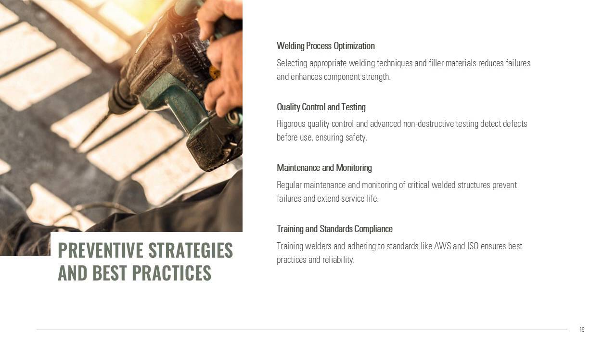Implementing rigorous quality control during fabrication and using advanced non-destructive testing methods ensures defect detection before service. Regular maintenance and monitoring of critical structures further enhance safety. Training welders and engineers on best practices and adhering to international standards such as AWS and ISO are vital for achieving long-term reliability.